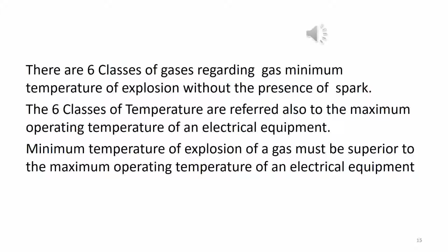There are 6 classes of gases regarding gas minimum temperature of explosion without the presence of spark. The 6 classes of temperature are referred also to the maximum operating temperature of an electrical equipment. Minimum temperature of explosion of a gas must be superior to the maximum operating temperature of an electrical equipment.